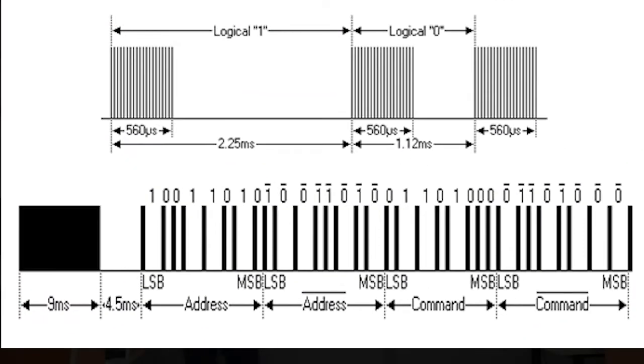This protocol is followed by LG, like my TV at home follows the NEC protocol. So what it does is, first, this is the start bit I was talking about, 9 milliseconds plus 4.5 milliseconds. So continuously, it sends this pulse initially. Then my TV knows, okay, something is going to come, I have to receive this now. And then comes the address bits followed by the not of the address bits, right? 8 bits of address followed by the not of the address.